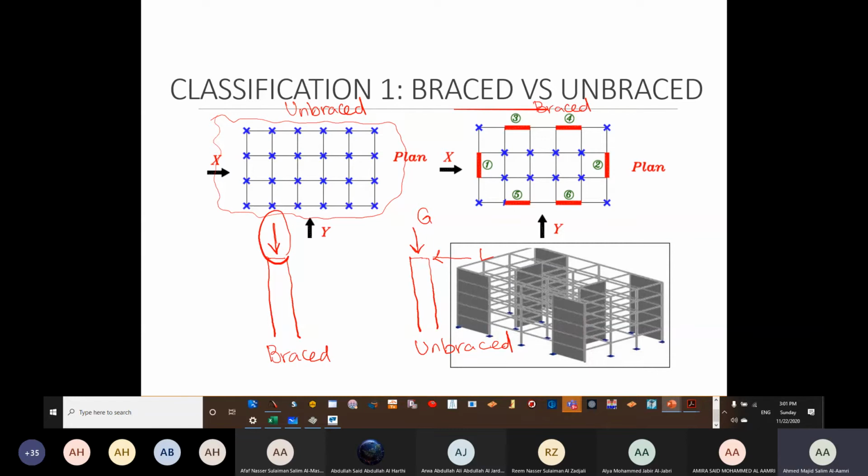But if we are designing for more than 3 stories, normally the municipality will force you to have a lift. Now the lift consists of shear walls. Shear walls joined together, and we called it a core wall, if you remember. A core wall is a very heavy element. It's a full concrete wall which will restrain your building; let's say not stop, but it will reduce the movement in case of any lateral loading of wind and earthquake, because it's very heavy.